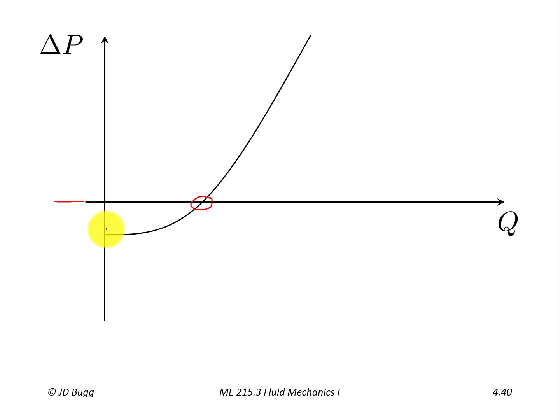So that means that the fixed system pressure, these ones, are driving the flow. So if we have Z2 smaller than Z1, for instance, going downhill, then this is a gravity-driven flow, and we can have a system curve that intersects this axis. So if the system curve looks like this in a gravity-driven flow, then that will be the flow rate.